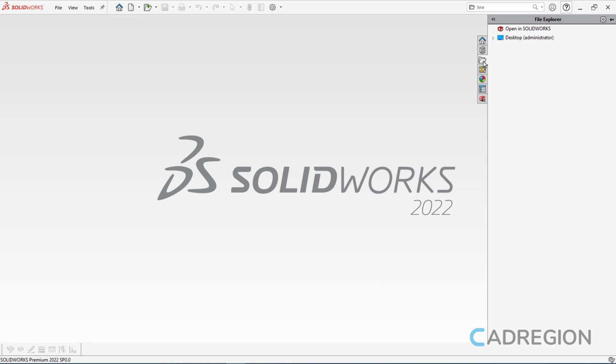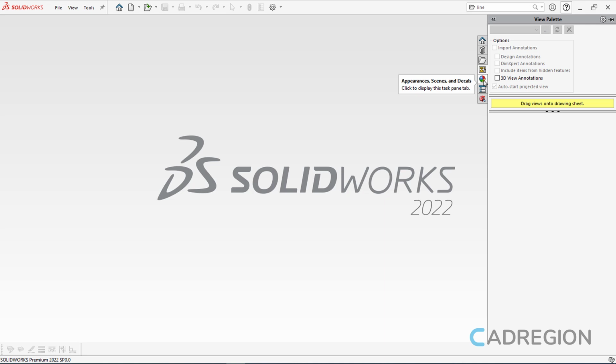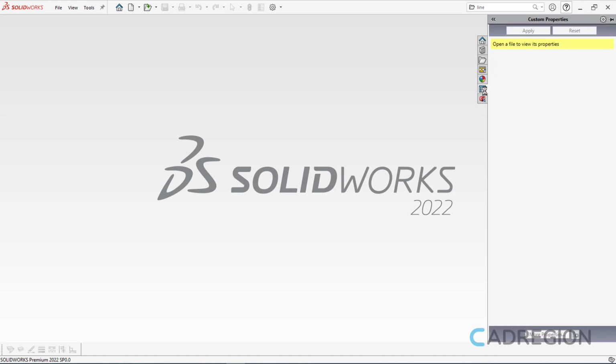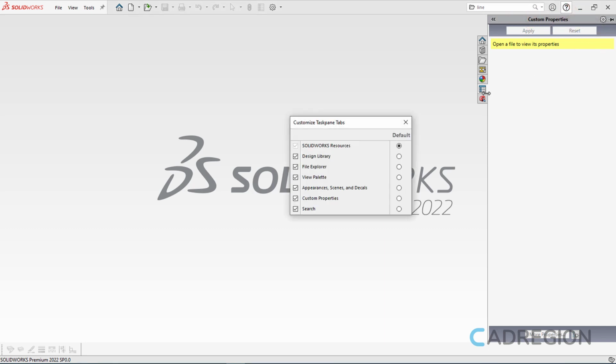From the View Palette tab, we can see several views of the object we have created. From the Appearances, Scenes and Decals tab, you can adjust the appearance of the object and you can change its material. Last but not least, from the Custom Properties tab, you can view and edit the properties of a file. You can manually adjust which tabs will appear in this box by clicking the gear icon. From the window that appears, check the tabs that you want to appear in the box.